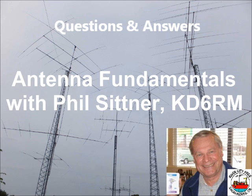for the frequency. As you go lower in frequency, the antenna needs to be longer. As you go higher in frequency, the antenna needs to be shorter. And it demonstrates that vividly. So this is a graphical representation of what happens to your SWR curve as you make the antenna shorter or longer. And I'm making it shorter or longer by manipulating a capacitor. But in real life, exactly the same thing would happen.